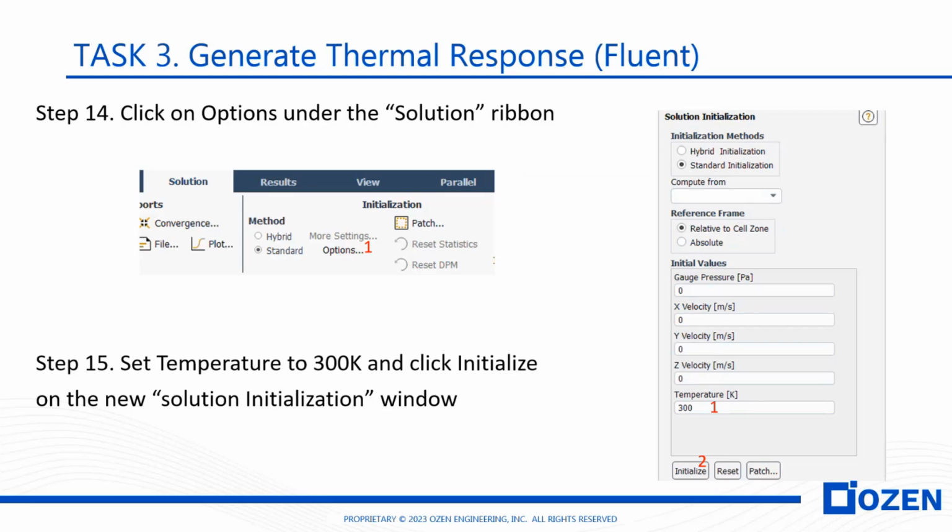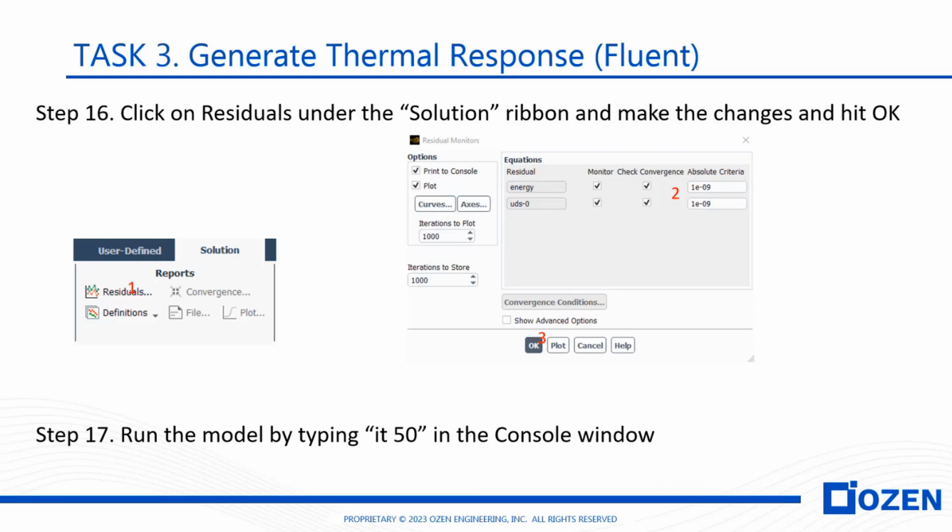We defined our material properties, the battery model, boundary conditions. Now, what we do want to do is initialize the solution, and that's the procedure in CFD. You do start with the initial solution. You do iterations to get the flow and thermal field to converge. So this is our first step to start solution.